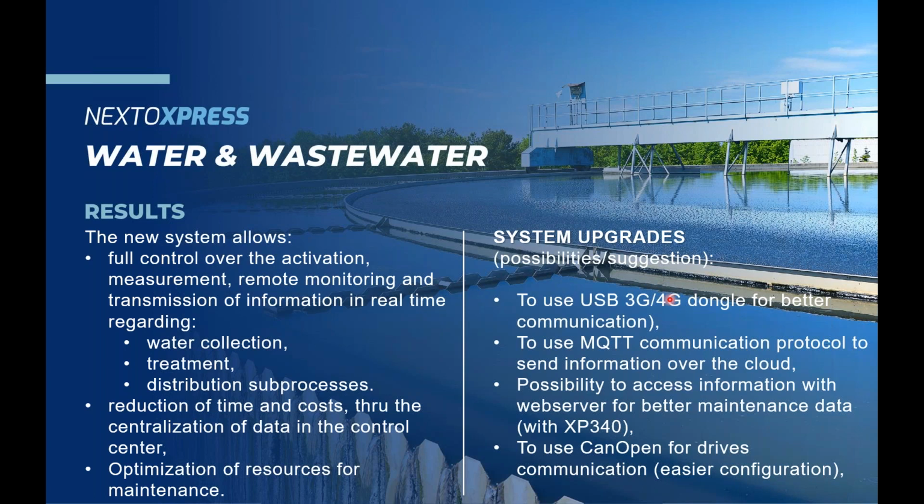Another thing: instead of using Modbus up to the data center, I recommend using the MQTT communication protocol. It's much faster and much more reliable. We save a lot of data over the network, and we can go directly to a database. We are using a lot of MQTT via 3G and 4G at the moment.